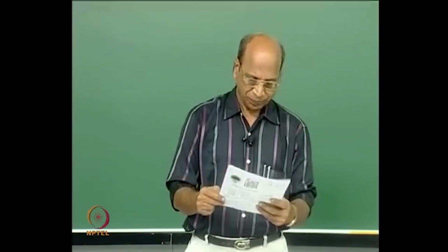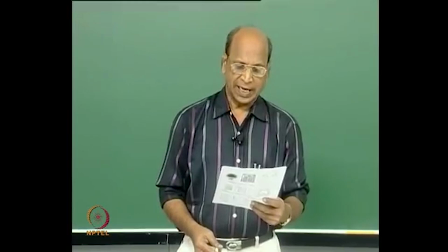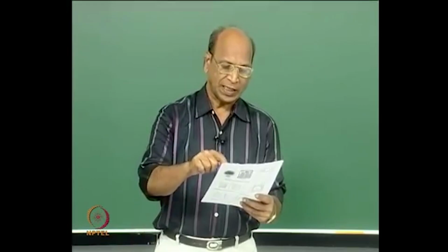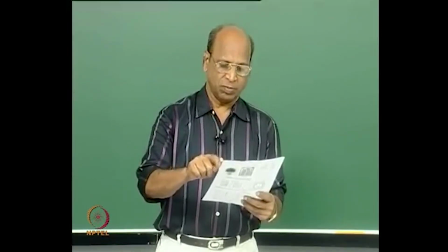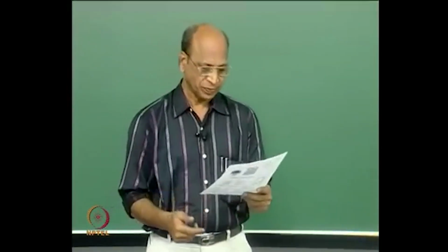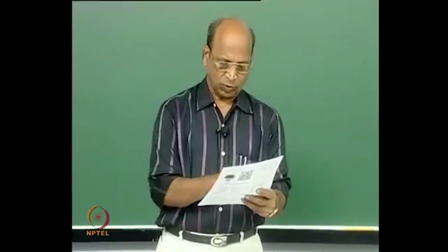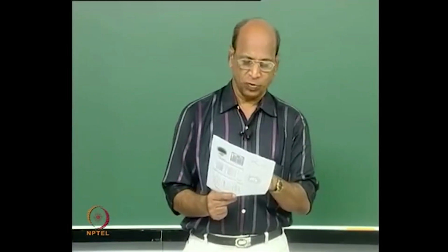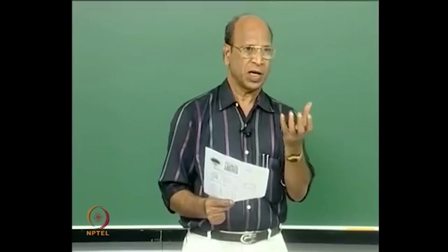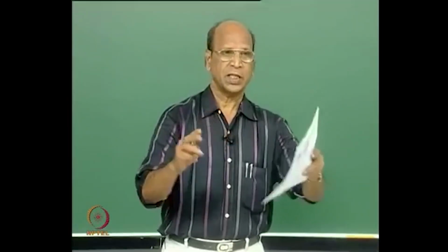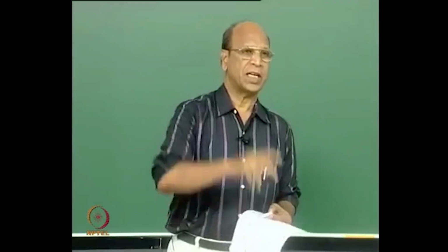And figure 3, if you take one bubble, what is really happening in that one bubble? Before understanding that bubble, you can come to figure 4. This is what I explained to you yesterday. Figure 4, the first one, out of the 6 figures in the top row, the first figure has UBR equal to 0. What is the meaning? They are stationary bubbles, they are not moving, and the gas in the emulsion at minimum fluidization velocity is simply going through the bed. The bubble is stationary there.